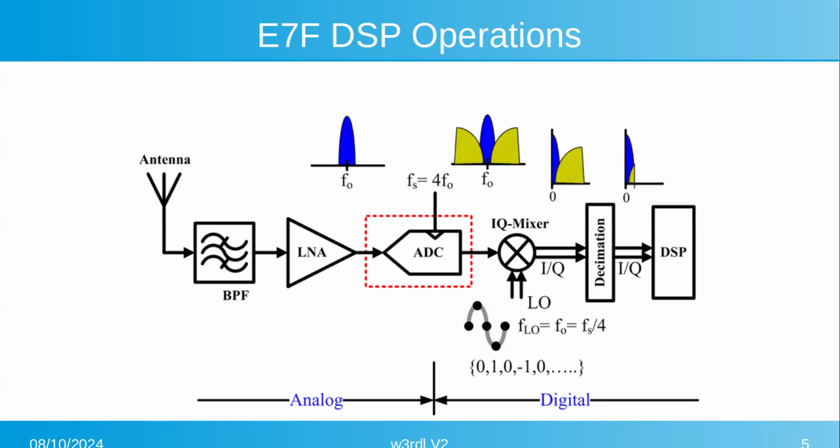Typically, it's done because we generate I and Q signals, which we'll talk about in a little bit, which you're essentially converting things to a sine and cosine form, where the cosine is 90 degrees out of phase with the sine. So that's what I and Q actually stand for. Okay, thank you. Mix those together and do all kinds of wonderful things. Thanks.